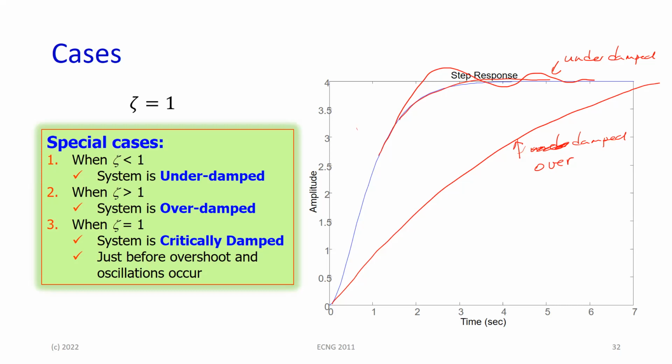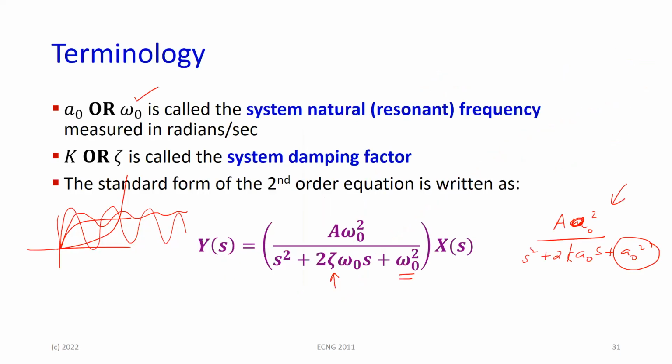So, questions? We covered a bit here. The crux of the matter is the variation of that transfer function with k. Once you understand that, that's the takeaway from this lecture. A general second order system has a form with a frequency of oscillation and a damping behavior. If the damping is too small, the system will oscillate at omega 0.